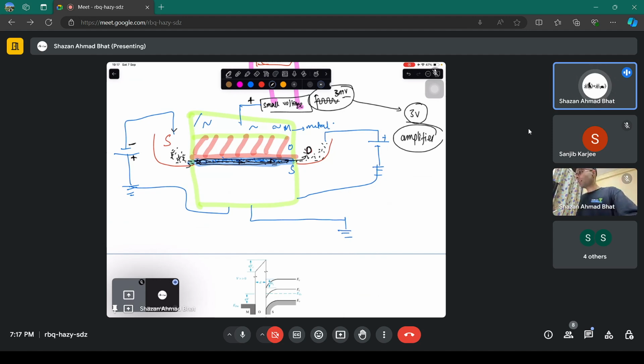Basically, any field effect transistor, or basically any transistor, is good at amplification. And one more thing it can do now is, apart from amplification, this amplification was not possible in diode. Remember this. The diode is not used as an amplifier. That's why you don't apply a small signal to diode and it gets converted to a larger signal. No. Why? Because you need a dependent source for amplifier. Now, what is that? I don't want to go into jargons right now here, but just think about it.